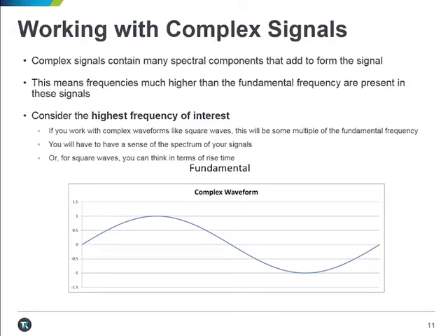In addition to understanding the concept of scope bandwidth, it's important to have a good understanding of the frequency components that go into your signals. If you're dealing exclusively with sine waves, then life is pretty simple. The highest frequency you're dealing with is the highest frequency of the sine wave you work with. However, if you're like most of us, you're going to be looking at signals like square waves or rectified sine waves, pulse or transducer output signals.